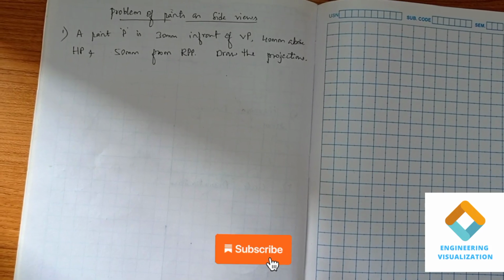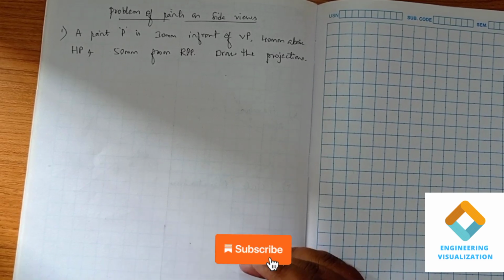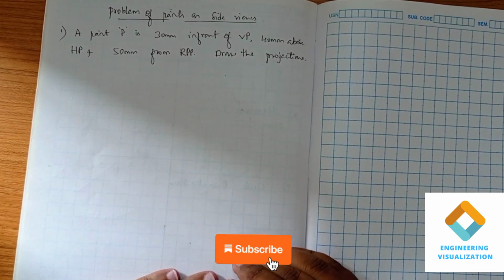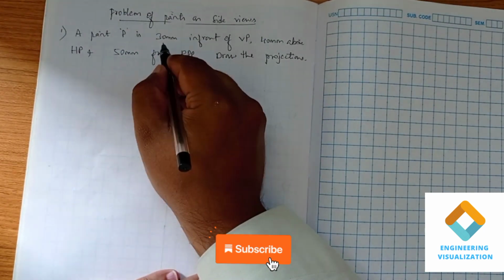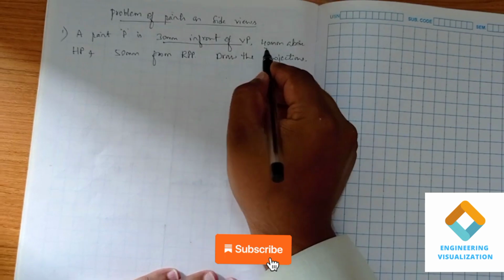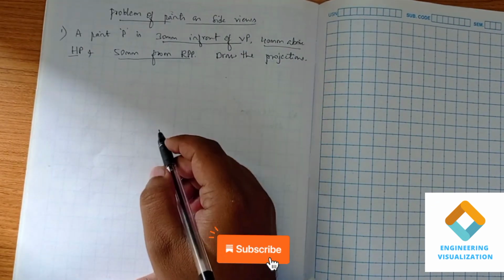Okay. Today we are going to discuss the problem of points on side views. So in this problem, we will be dealing with the side views here. So we will go with the question. A point P is 30 mm in front of VP, 40 mm above HP, and 50 mm from RPP.